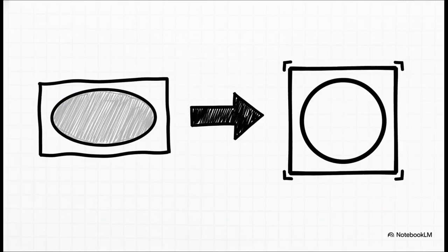Of course, a simulation isn't truly complete until it's formatted to communicate clearly. These finishing touches are all about aesthetics. We added a text label directly onto the gray sphere so anyone looking knows for sure it's a conductor. We set clear X and Z axis labels and give it a nice overarching title. But honestly, the most vital formatting command here is axis equal. Without that tiny command, MATLAB might stretch our plot to fit a rectangular window, making our perfectly calculated sphere look like a squished oval. Axis equal locks the aspect ratio, keeping our sphere geometrically true to life.